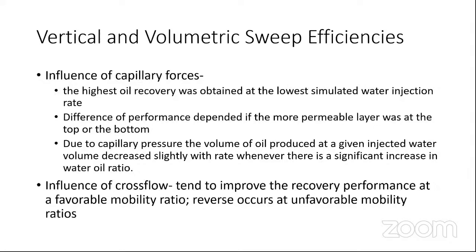So now I'll talk about the influence of capillary forces. The highest oil recovery was obtained at the lowest simulated water injection rate. The difference in performance depended on whether the more permeable layer was at the top or bottom. And then due to capillary pressure, the volume of oil produced at a given injected water volume decreases slightly with the rate whenever there's a significant increase in water-oil ratio. And then you have the influence of crossflow, which tends to improve the recovery performance at a favorable mobility ratio, but the reverse occurs at unfavorable mobility ratios.